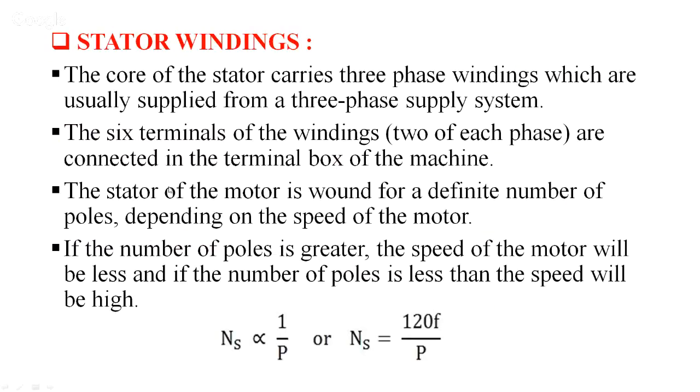Stator windings. The core of the stator carries the three-phase windings, which are usually supplied from a three-phase supply system. The 6 terminals of the windings, 2 of each phase. So there are 3 phases, R, Y, B: red, yellow, blue.